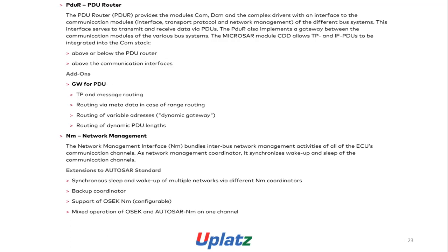The Microsar module CDD allows TP and IF PDUs to be integrated into the COM stack above or below the PDU router, above the communication interfaces. Add-ons: gateway for PDU, TP and message routing, routing via metadata in case of range routing, routing of variable addresses, dynamic gateway, routing of dynamic PDU lengths. NM, network management interface, NM bundles, interbus,